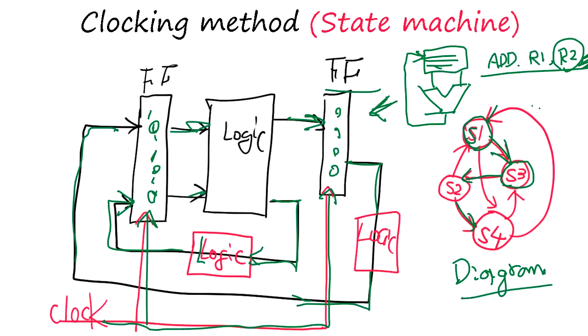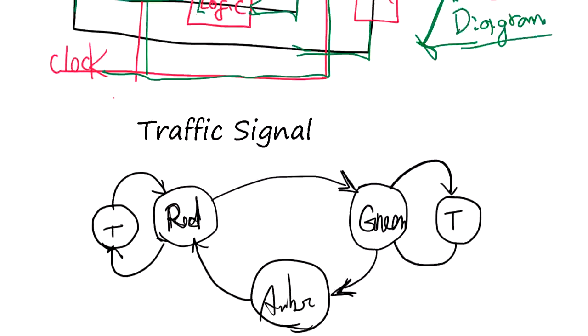And IC chip design for digital circuits becomes mostly making a state diagram and converting that into a logic array and registers. The logic array is created by software based on the logic equation. So the design itself is the state diagram and the logic equation.